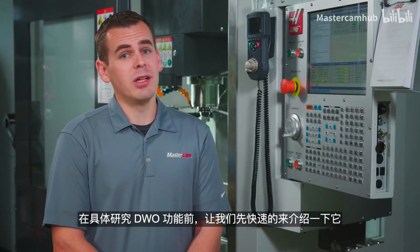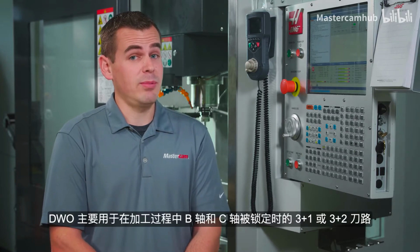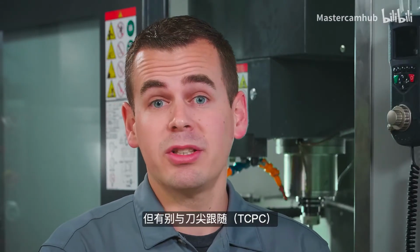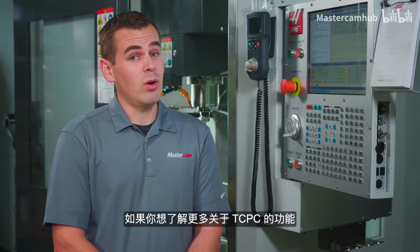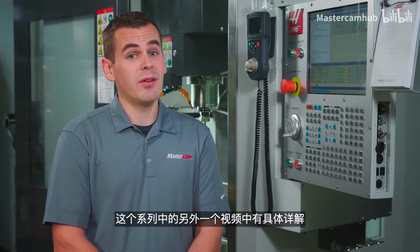Before we talk about DWO, we should take a quick moment to point out that DWO is used for 3+1 or 3+2 toolpaths where the B and C axes are locked during cutting. And it shouldn't be confused with tool center point control. TCPC is for full simultaneous 5-axis toolpaths. If you're interested in more information on TCPC, there is another video in this series which covers it in depth.